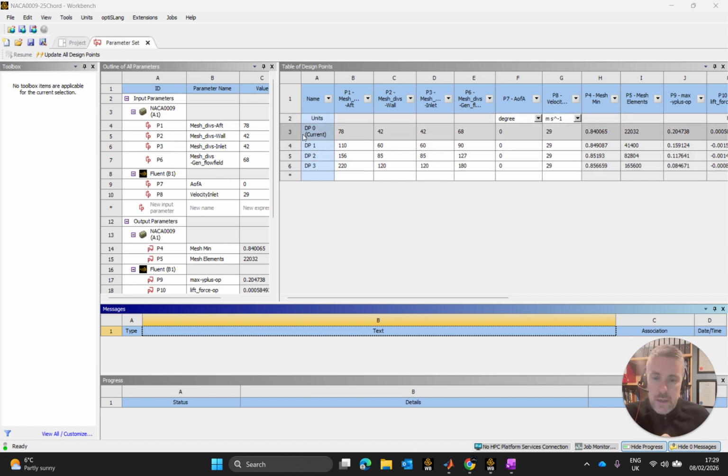So in our last video, this is where we finished off with 4 design points. We initially had a coarse, a medium, and a fine mesh, and out of the fine mesh, we did get a fairly good GCI value, and our apparent order was decent enough. But we did refine it one more, and when we did, we were still at a level where numerical inflation didn't take hold and our apparent order value did not explode to something nonsensical, whilst our GCI index came down to a very attractive level, and we decided there that DP3 is the design point that we're going to run with.